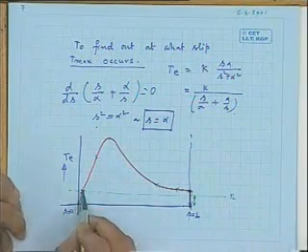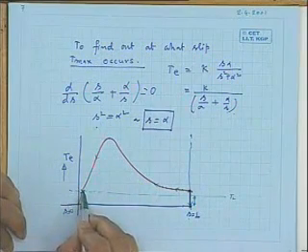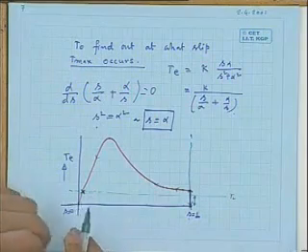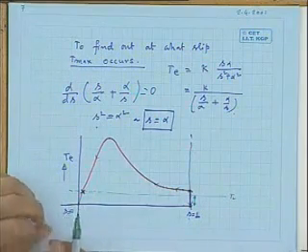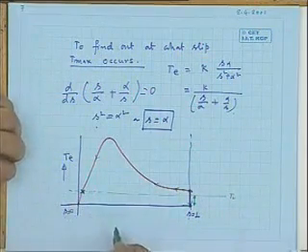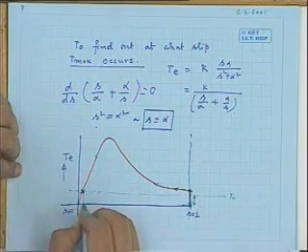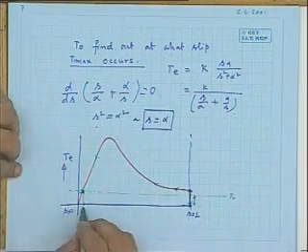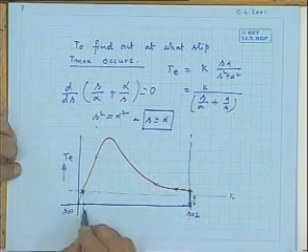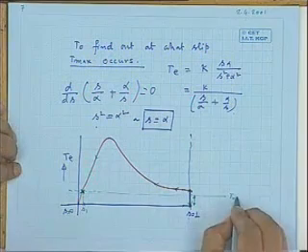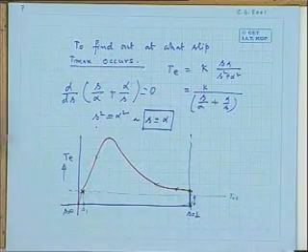The machine operating point will move, and it is at this point you will find TE is equal to TL, and the machine will operate at a constant speed. And at what speed will it run? It will run at a speed or slip that you can read from this graph, and the machine will run at this slip S1 when the load torque is TL1.